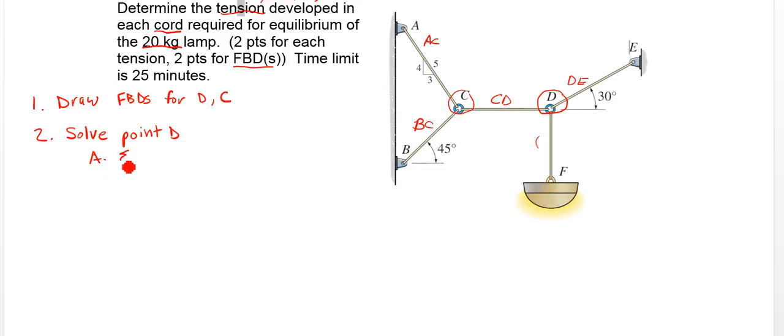A, sum the forces in Y set equal to 0. B, sum the forces in X set equal to 0. Then we will move on. Step 3, we'll solve for point C. There we go. All right, so that's our approach.